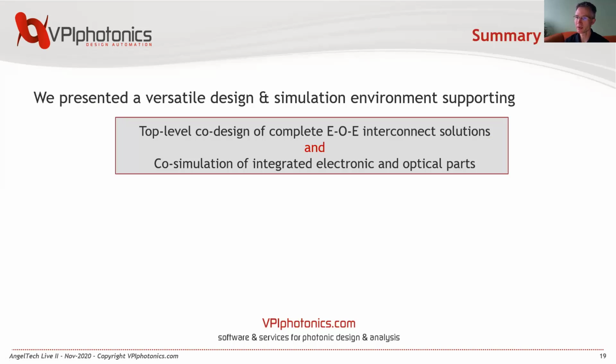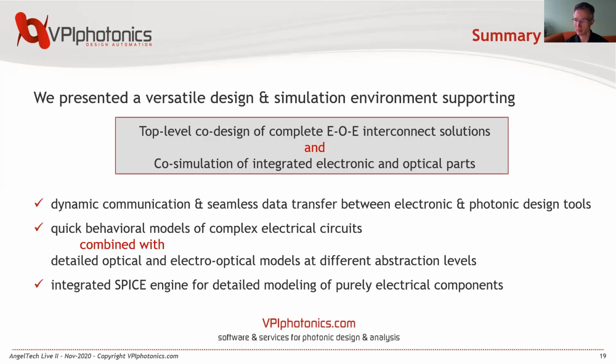So in summary, I presented to you a design and simulation environment which accounts for the top-level co-design of the complete EOE interconnect solutions and of the co-simulation of integrated electronic and optical parts. This is enabled by the dynamic communication and seamless data transfer between individual design tools. And this allows you to account for quick behavioral models of complex electrical circuits, and doing this together with detailed optical and electro-optical models. If you want to integrate purely electrical components into the modeling environment, you can do this easily by an integrated SPICE engine.